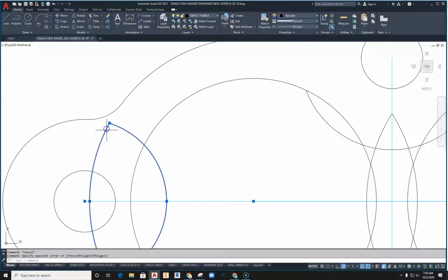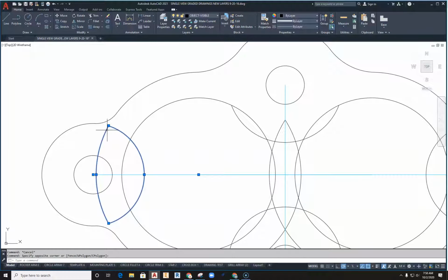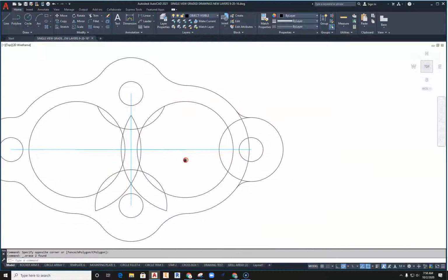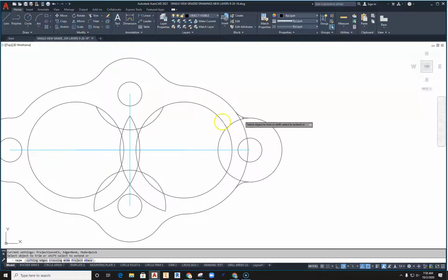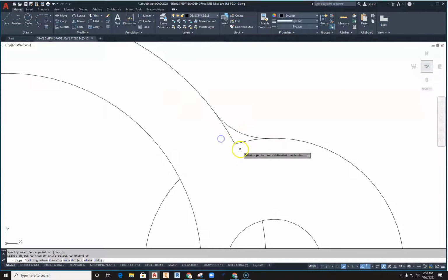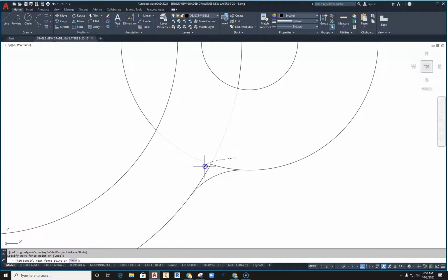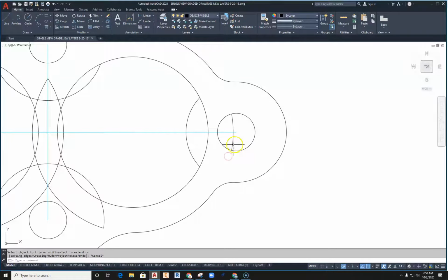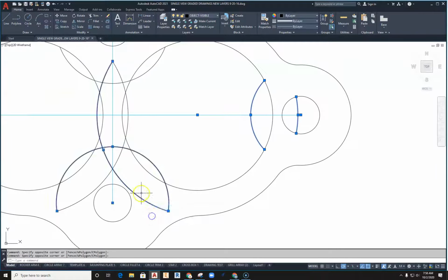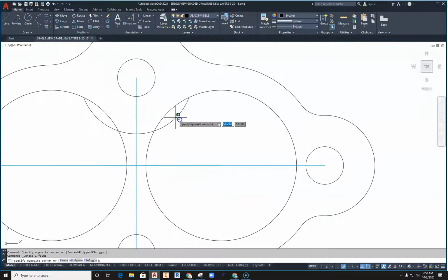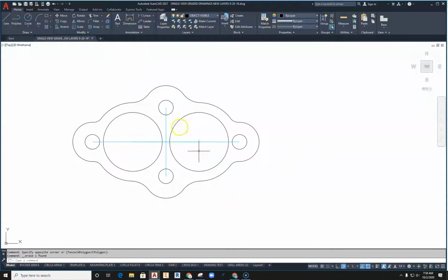If I do a quick little panning window across that chunk, I can delete it. Then you're not trimming more than you need to trim. So grab that trim tool again. Come down here. We'll trim this out, trim this out, and trim this. There we go. Then I'll click on this one, and this one. Do little panning windows to get rid of this mess. Don't try to get it all in one fell swoop. You'll work your way through and grab them.